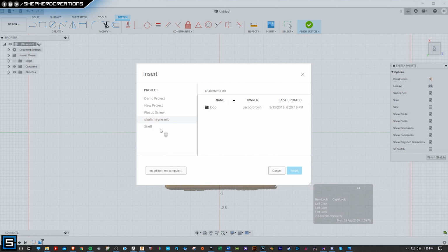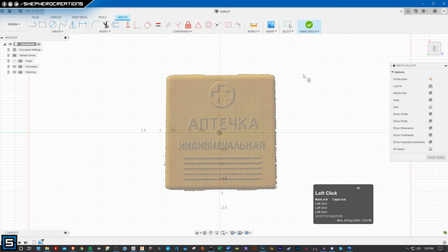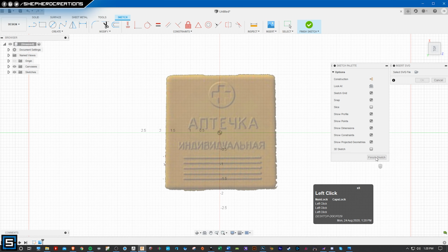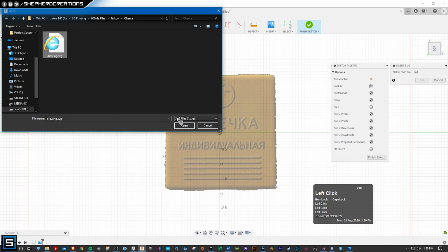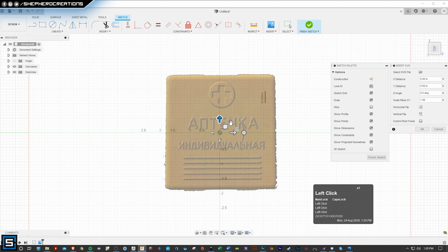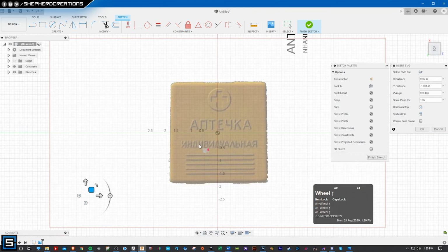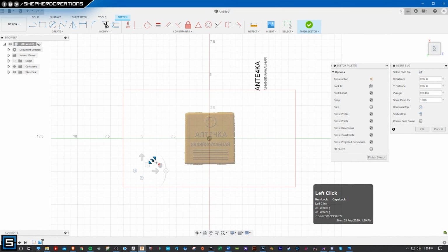All right, now that we're back in Fusion360, I'm going to locate the files on my PC, grab that SVG file that I just created in Inkscape, open it up, scale it up to the size that I need, rotate it, and kind of get it into position. It's not absolutely necessary to get it into the exact position in relation to the image on the background here.